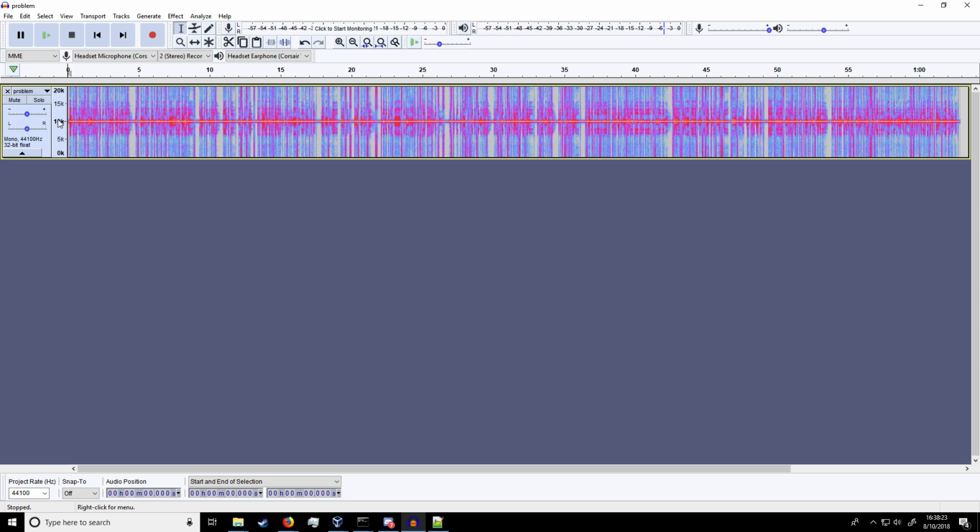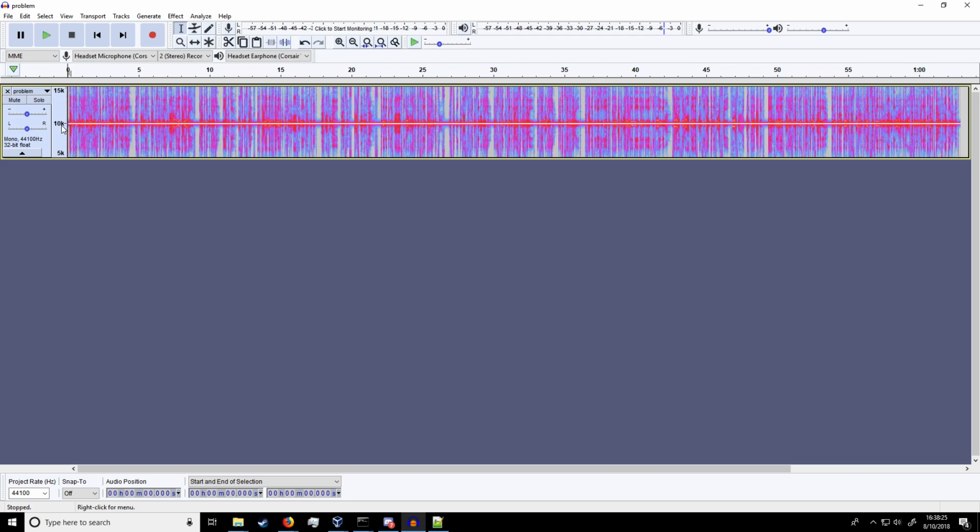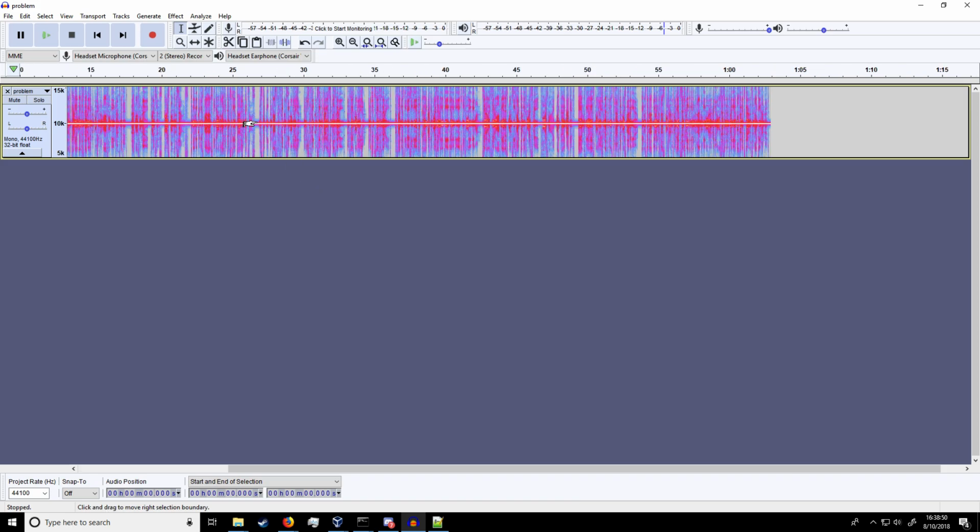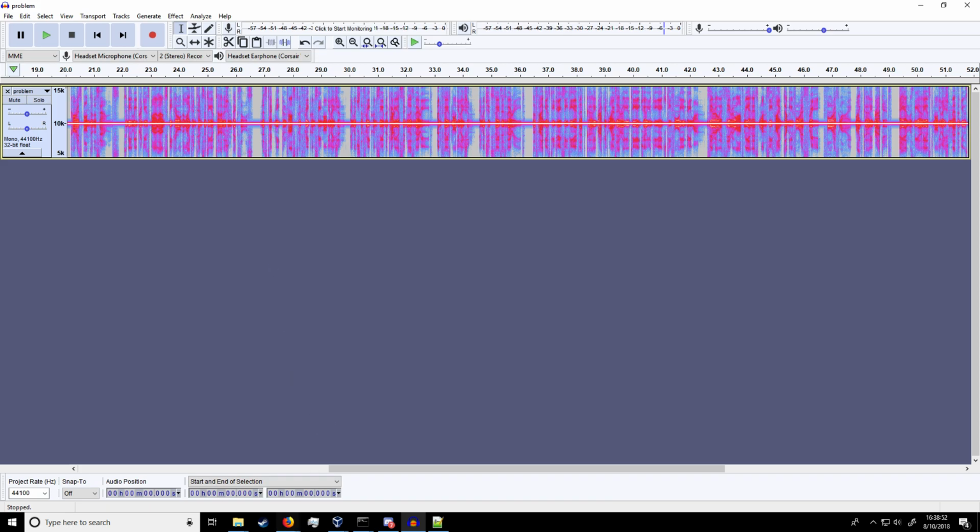So let's move up to where it looks like there's some data, and it doesn't look like there's anything written here. But to me this looks like AM modulated audio in the frequency domain, where it's scattered about 3 kilohertz to either side, and we have what seems to be a carrier wave at 10 kilohertz. So my next thought was, this is probably just AM audio modulated with a carrier frequency of 10 kilohertz. If we can demodulate this, we should be able to get the message back.